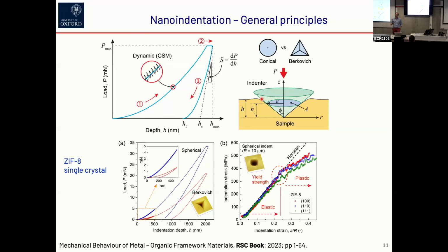And what you do is you have a very hard probe, typically diamond or other hard solids, which are well defined in its geometry. Then by squeezing or penetrating the surface, we track the load change as a function of penetration depth. So it's quite parabolic for a conical or Berkovich type indenter, and then you do the unloading.